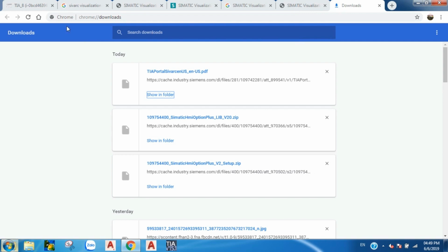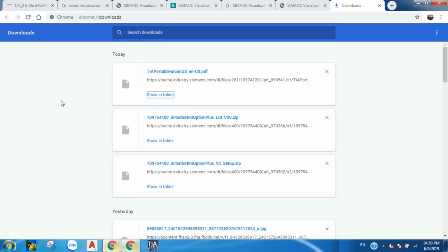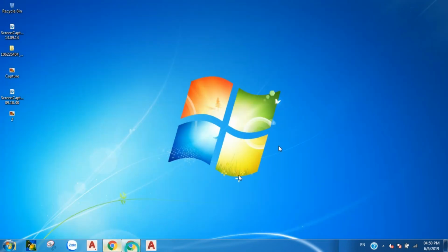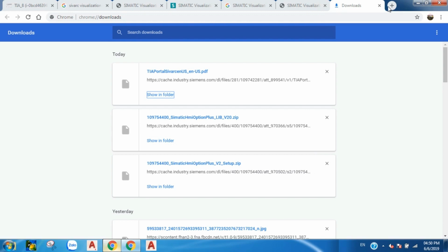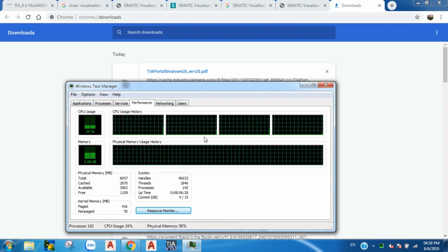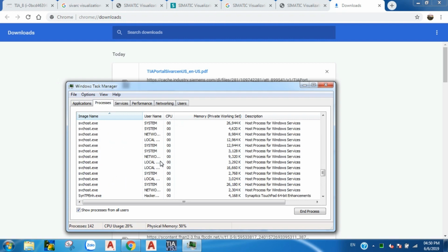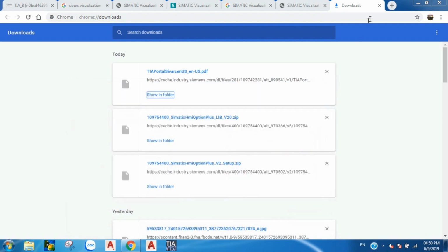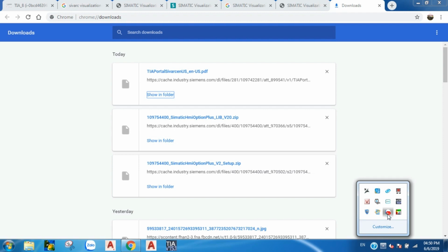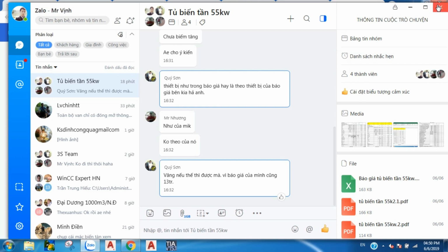I would expect now that in my already generated screen, I also see my trend control in here. And when I go to the properties, I should now see that the data source for my trend is my FB tanks dot trend value, which is written in here.